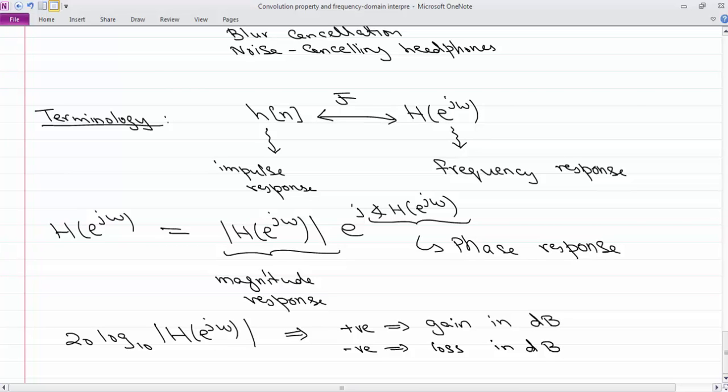Because all it is saying is your input signal will have certain frequencies. There is no absolute number to the frequencies that you will input to the system. So what we are really concerned about is if you input a frequency at this level or at this level, what's the scaling of that? If it's 2 times, 4 times, 8 times. So that's why we like the dB scale. You know, we say, oh, it's going to give a gain of 3 dB. So it's going to increase that frequency by a factor of 2, whatever was the input frequency strength. Right? Or it's going to decrease the input by a factor of 2, so it's going to create a loss of 3 dB. So you don't talk about absolute values, so that's why you often see these plots in the dB scale. Okay. And of course, if you are ever hitting 0 in your frequency response, then you will see a big dip in your dB plot.